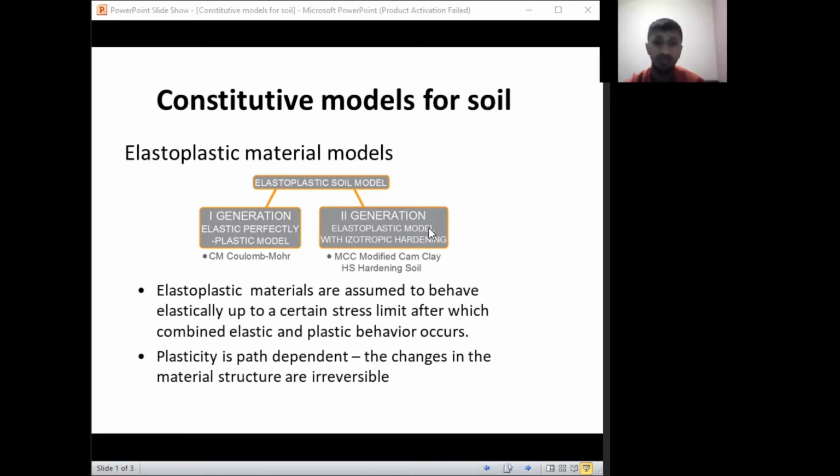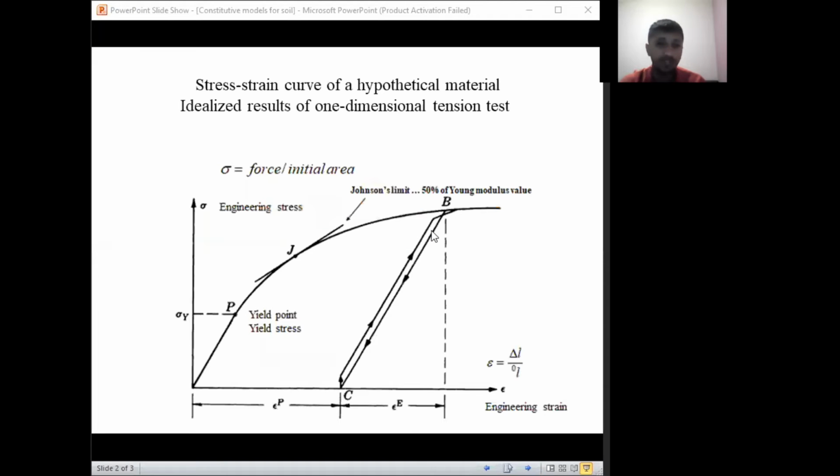These models can be grouped into linear elastic, non-linear elastic, variable modulus, elastoplastic, and hypoplasticity. Solutions in constitutive modeling have been based upon Hooke's law of linear elasticity for describing soil behavior under working load conditions, and Coulomb's law of perfect plasticity for describing soil behavior under collapse state. Generalization of Hooke's law and Coulomb's law is formulated in a plasticity framework and is known as the Mohr-Coulomb model. However, it is well known that soil is not linear.